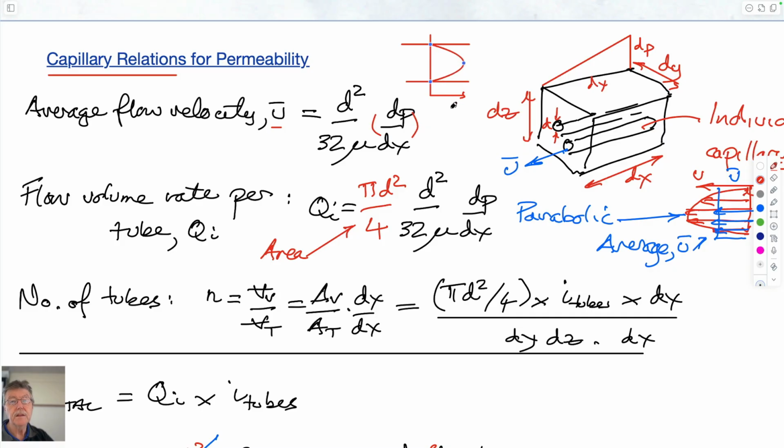Oh, that's pretty good. So if you solve for velocity of flow, then the maximum flow velocity is in the middle of this pipe. The zero flow velocity is at the side. If you solve the differential equations for momentum and mass conservation in this geometry, you get this expression. This expression says that the velocity as you go across this pipe is anchored to zero velocity at the walls, where it's a no-slip condition, and a maximum velocity at the middle, so it's a parabola.